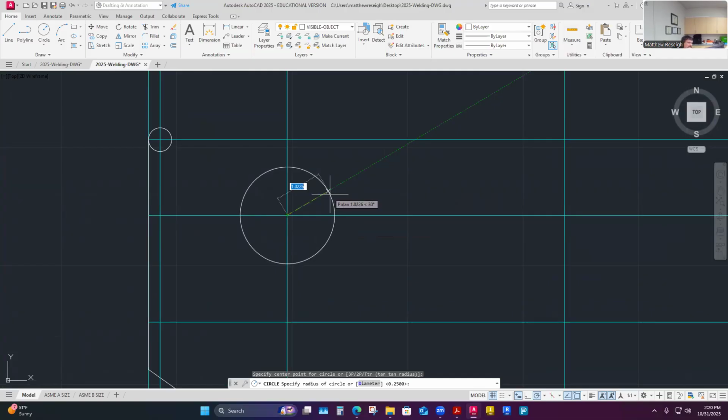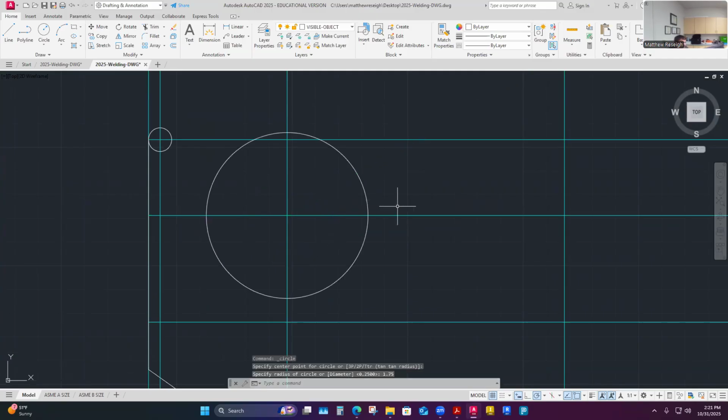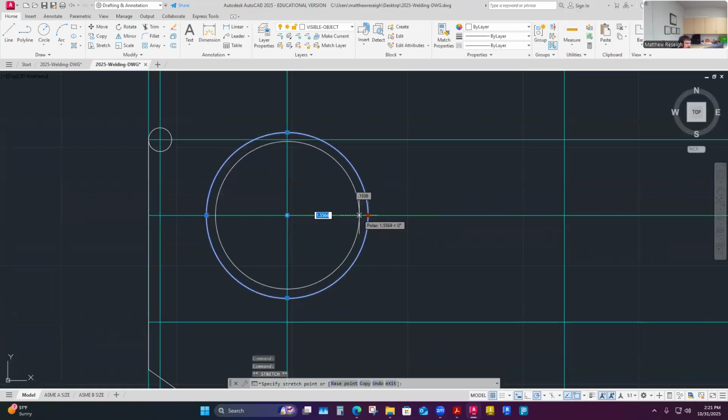And then just type in the dimension, 1 3/4, right? 1 3/4. And then hit enter. That's the end of that command. If you do it wrong, this is changeable. I mean, you can grip this and try to pull it in, and I can get control over that radius again, 1.75. So if you drop it wrong, remember it's modifiable with one of those grips.